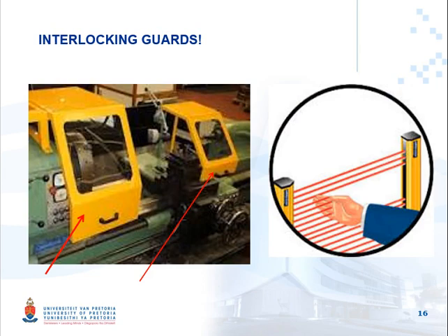Here you see interlock guards. Those are for some CNC machines. You see that sometimes there are no guards, so I can't say that I'm not going to provide my employees with a guard, but at the same time give them something to protect their eyes. When I can mitigate the risk with some kind of engineering revision, I need to do it.